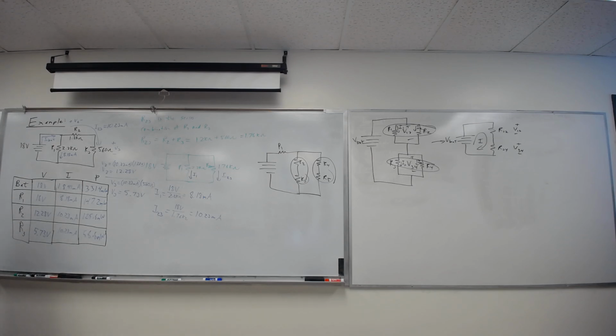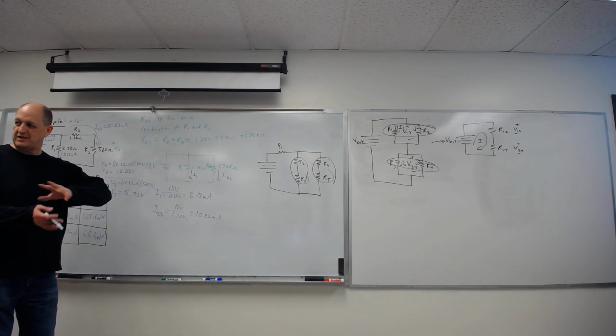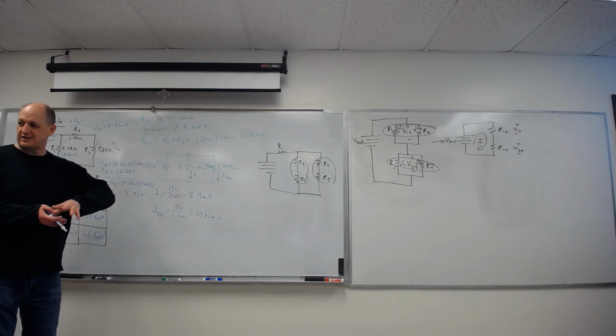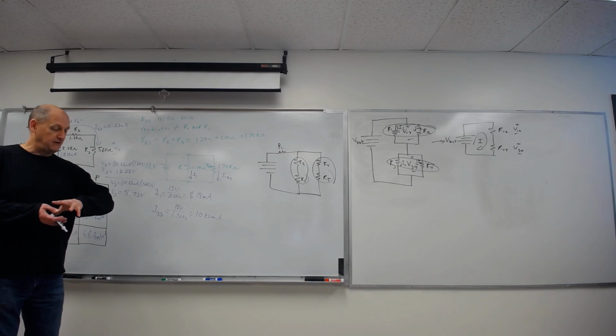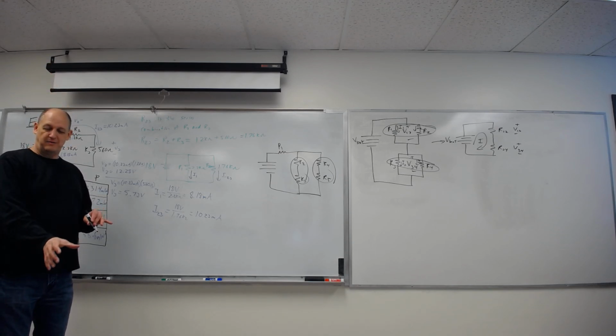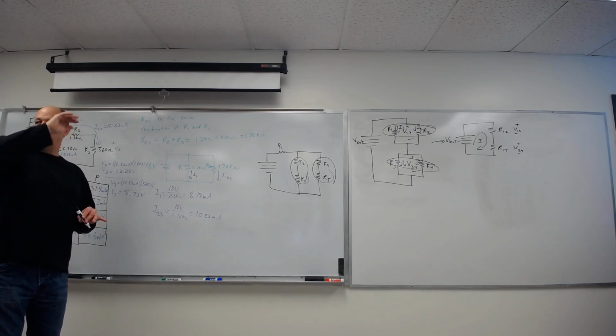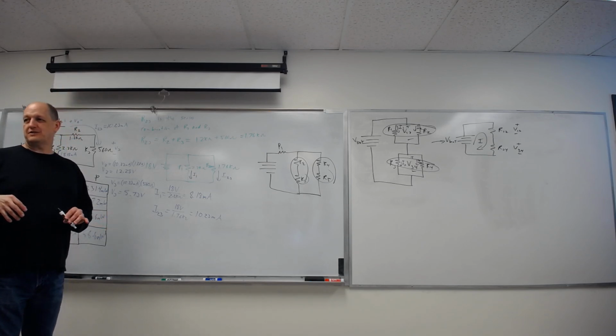And you work it. So it's always reducing your total number of resistors by finding series and parallel combinations to simplify to the point you can work the circuit. And then take those voltages and currents you find in that simplified version and just work back. What I do is I just lay my schematics down the page, and then I just start working back up the page, doing Ohm's law to find all my voltages and currents.